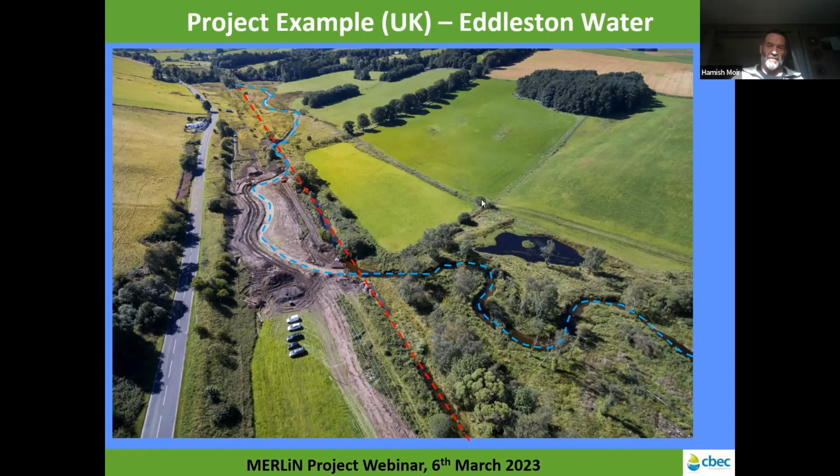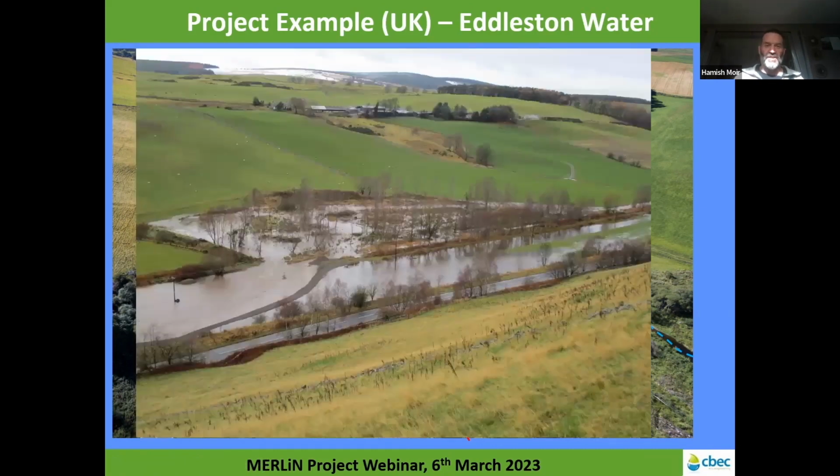So here we have a bund. You see this bund here. This protects this field from flooding up to a certain point. Now, you get to a certain size of flood and it's overtopped. And here you see the site in flood. So here you see the special field protected. Under this sort of moderate size of flood, it's entirely dry. So we're meeting that design constraint.